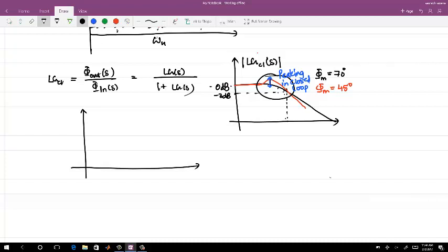When I say the ringing in the step response, it settles down after a long time. It will ring. Now, how exactly does it translate to jitter? That would be a little hard to say here. Let me say all these noise analyses are small signal analyses.